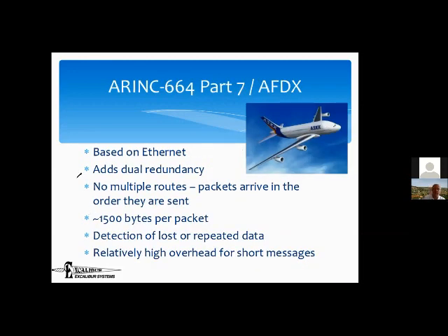Here's another example of a bus, the AFDX, which is currently used on the Airbus 380, probably a few others, and Boeing also, if they're not already using it, is certainly planning to use it. It's basically Ethernet. About 20 years back, Airbus and Boeing both decided that they deserved their own bus. They're two of the biggest companies in the world, so why shouldn't there be a special avionics bus? They made one, and they called it ARINC 629, and it was custom to exactly what they needed.